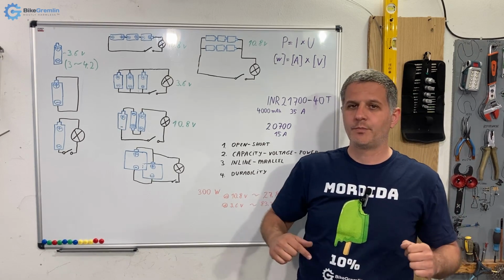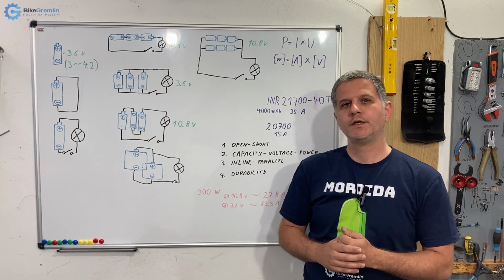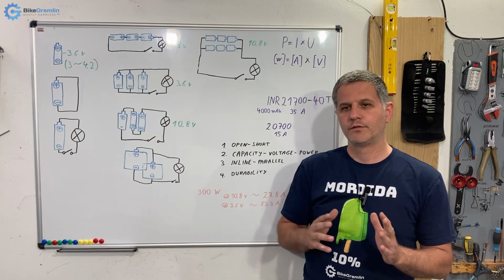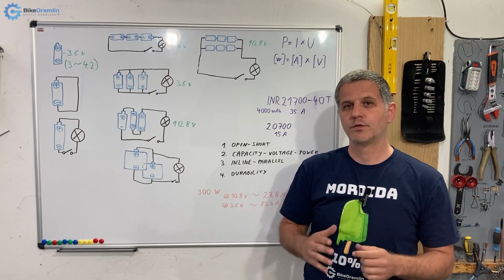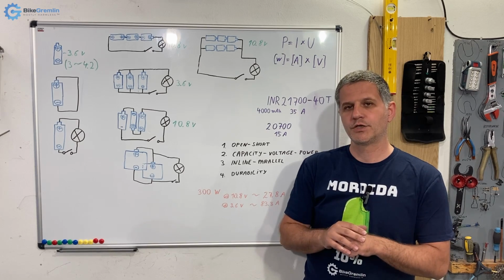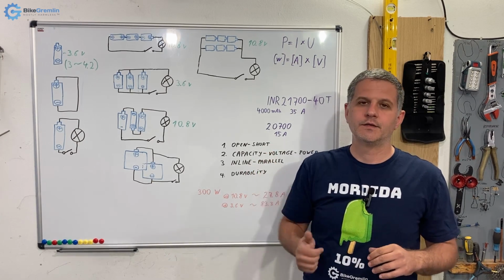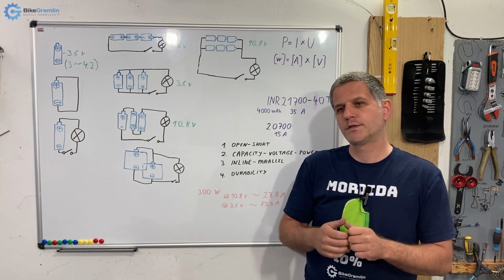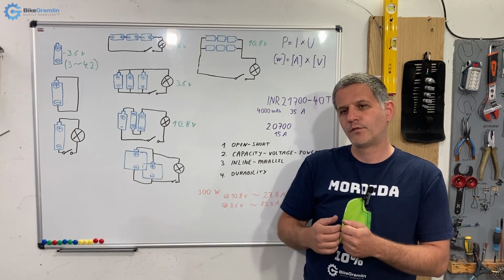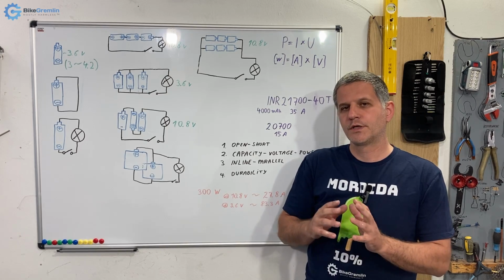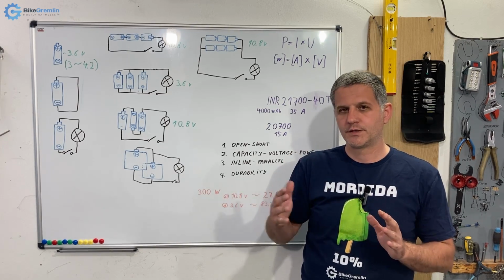Now what about topping up? Generally, all batteries have a limited number of charge and discharge cycles. So whenever you put it on a charger to recharge it, you've used up one cycle. It doesn't really matter if you've just been charging it for 5 minutes or for 50 minutes. It will degrade to a certain degree in terms of total charge cycles.